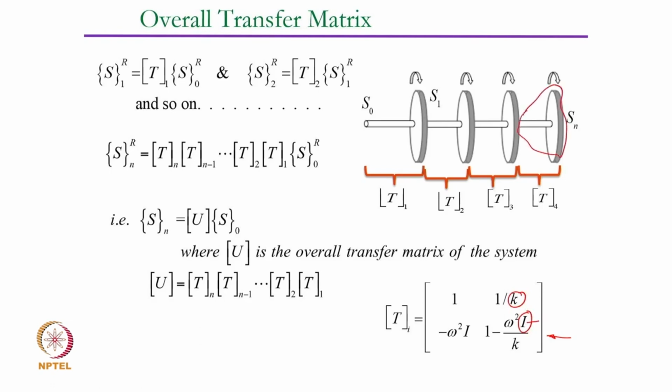In that gearbox, you know each gear and its dimensions, the material properties and all. So you know the inertia value of that gear, and the shaft connecting to the next segment, you know the dimensions of the shaft, so you know the stiffness of the shaft, knowing the material properties. So that way I and K is known for your system.